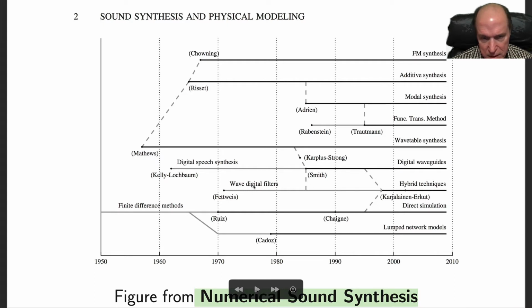So here's wave digital filters, which is a wave-based approach, and it's a very interesting case of a wave scattering formulation of a lumped system. So it's essentially a wave environment where the speed of wave propagation is infinity, which is very unusual. But it's got wonderful properties because of the scattering formulation. It ends up having excellent numerical properties, for example.